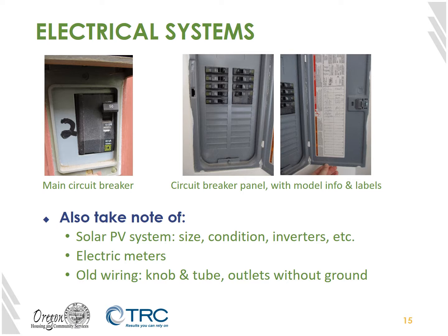It is also important to keep an eye out for traces of old wiring. If knob and tube wiring is visible in the attic, it is unlikely to be in use, but it may still be connected to the system and will need to be removed before insulation is added due to risks of fire.